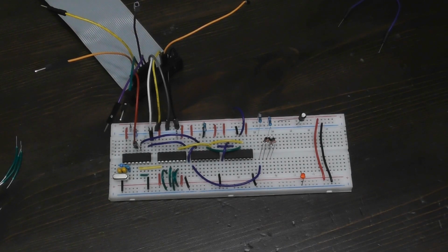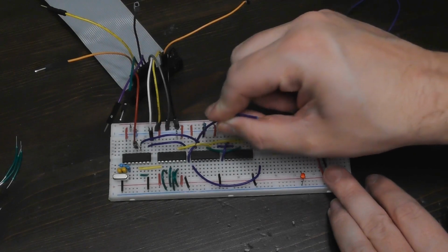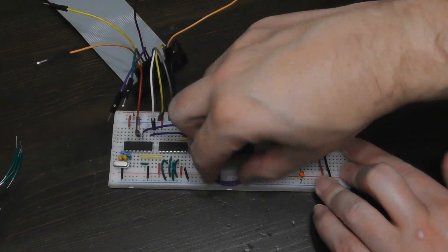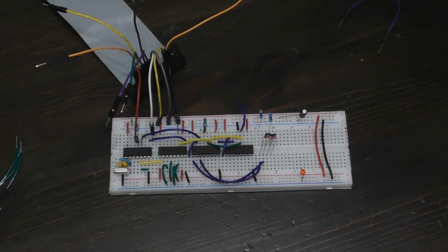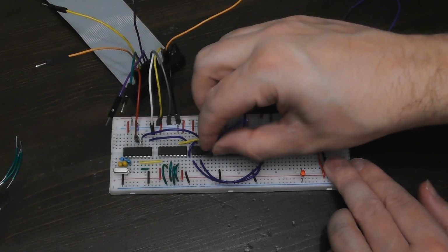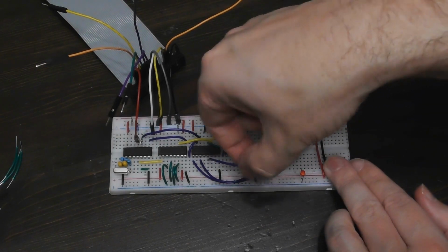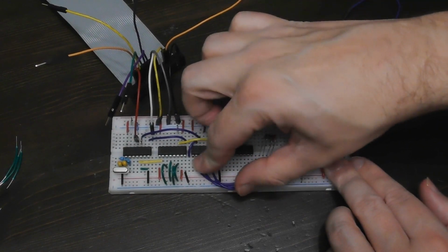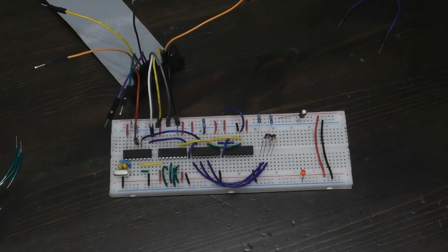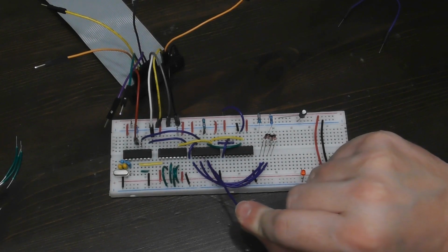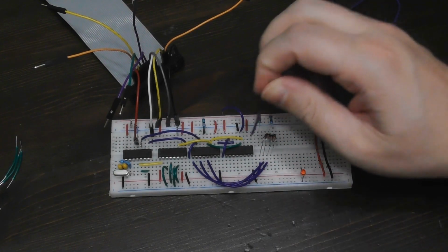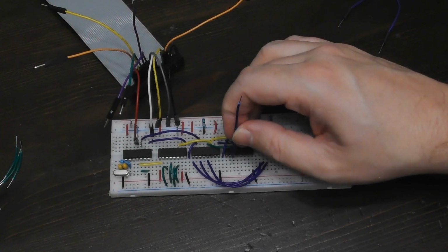And then I want clock pin 1. And remember, the data and clock are interspersed here, so clock pin 1 is the next along missing one. And that will go in here as well, into the next diode. And then I think it was clock 2 next. So this is essentially 3 clock bits in a row, and this comes from the 3 zeros in the C7 clock byte, and that's kind of what I'm filtering for here. And the other one I want to pull from the data byte, and it's going to be bit 5. So bits 0, 1, 2, and 3 are on this shift register for the data byte, and then bit 4 is here. So bit 5 will be the 3rd pin of this shift register.